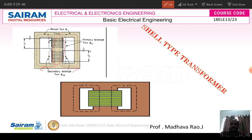If you place the high voltage winding near to the core, the insulation material and the insulation cost of the transformer will be increased, because we need to give more insulation to the core. To avoid that and to reduce the insulation cost, we always place the low voltage winding near to the core, and sandwiched between the low voltage winding we place the high voltage winding. Okay, so this is about